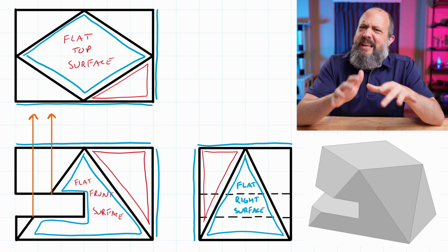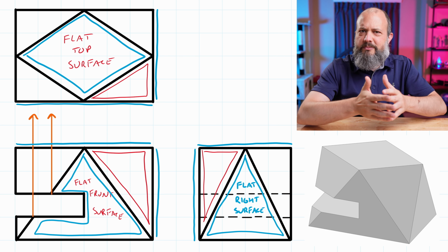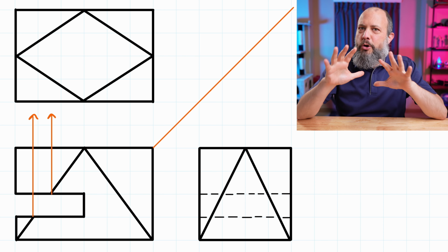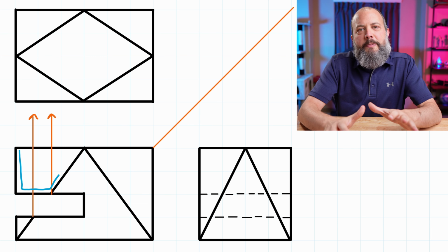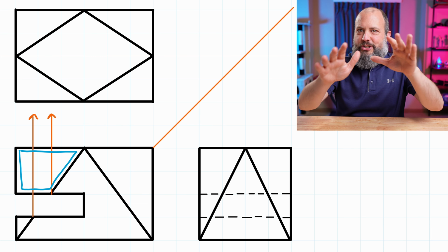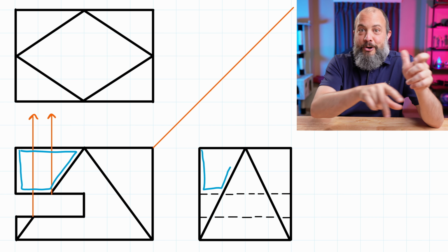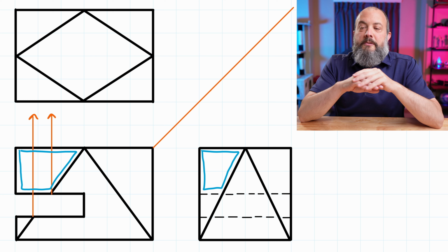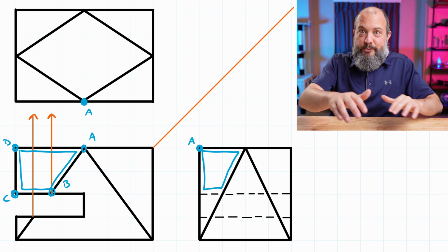And so there's definitely going to be a lot missing on the top view where the hole passes through the angled triangle. I already said that oblique faces are visible from all three sides, front, top, and right view. So instead of viewing these as a triangle with the cutout, let's actually just look at this blue shape, just the four-sided quadrilateral, right? So points A, B, C, and D, they should be visible on all three views.